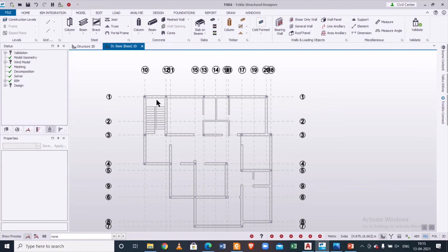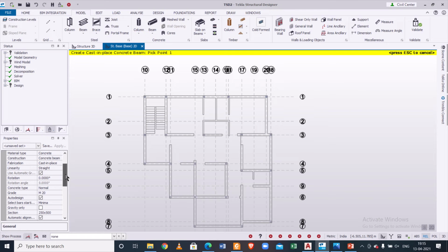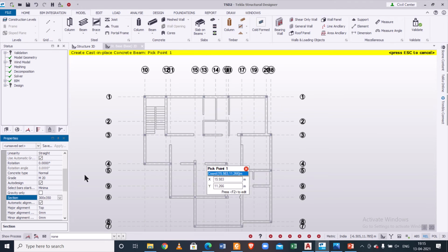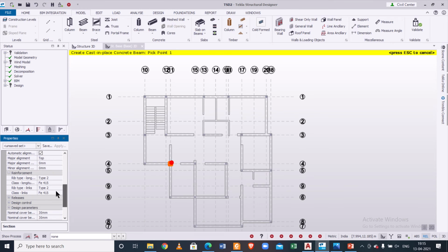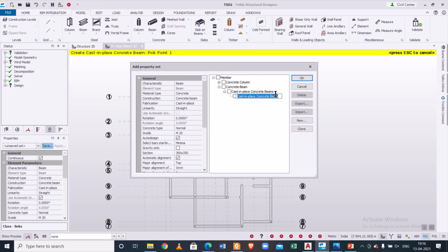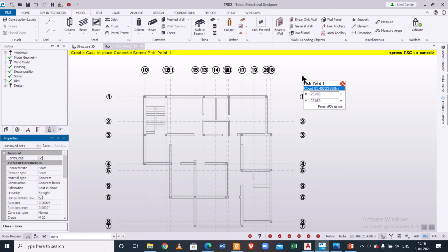At the plinth level, we'll be providing beams also for that size only. So it will be 300 by 300 first, or 300 by 350, or let's try 300 and 300 first. Okay, we'll go with 300 by 350, with this FE 500. Let's do this FE 500, and then we'll save this as B 300 by 350 for the laterite stone blocks.